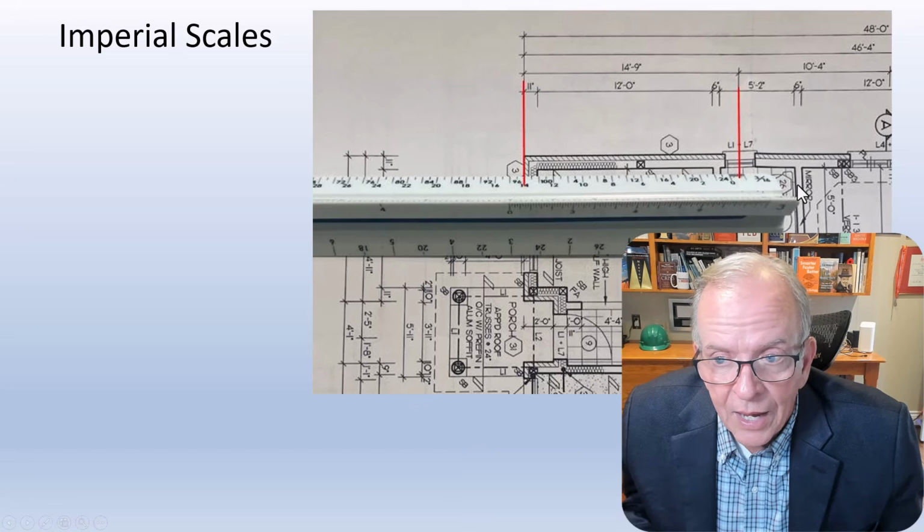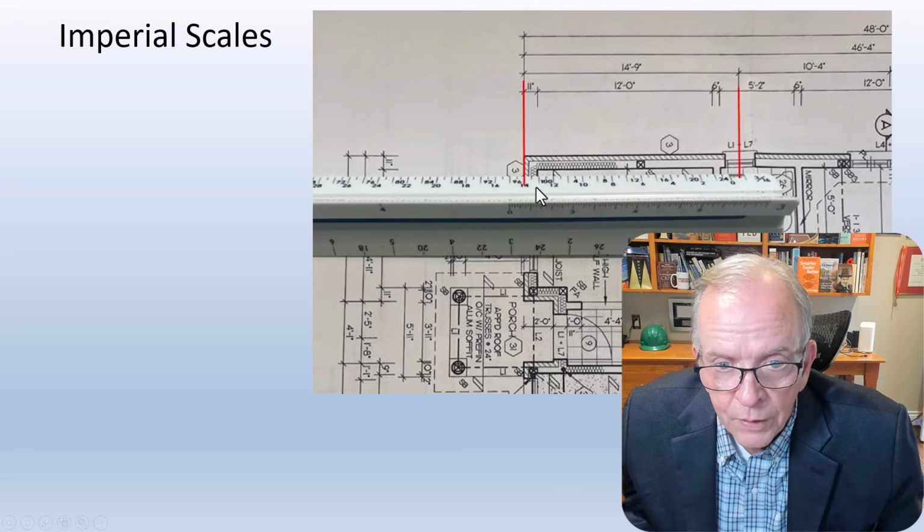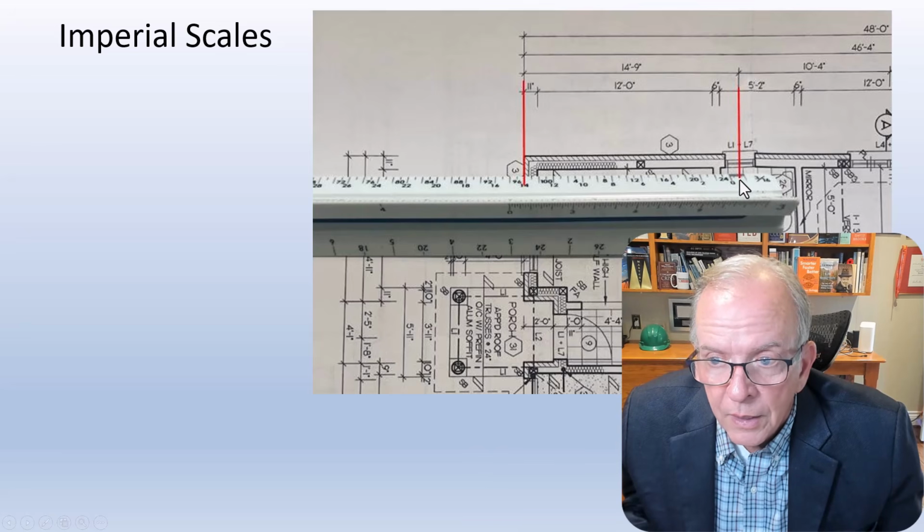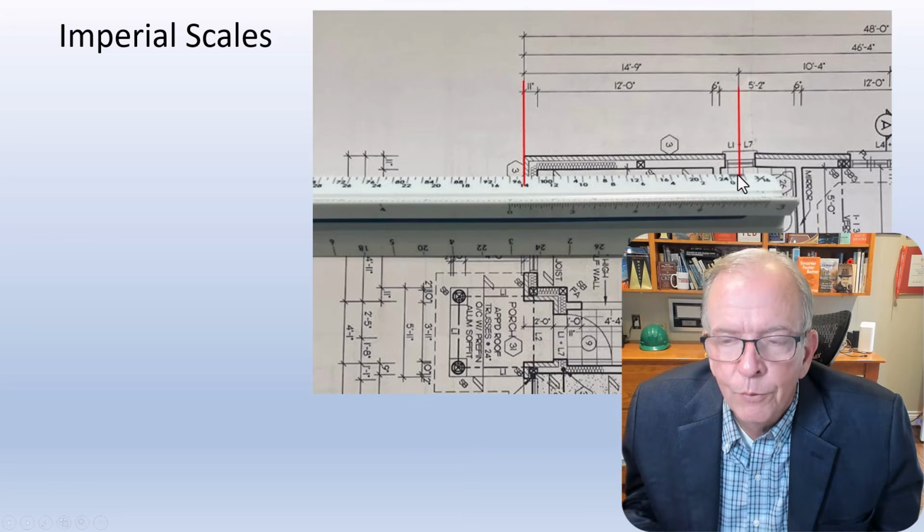And you could lay it down and you could say, okay, I'm using a 3/16 scale, right? So there's 2 foot, that's 1 foot then. There's 2 foot, there's 4 foot, that's 3 foot. Okay, 12, 14 foot. So coming from this line, 14 foot to this line here, I just overdid it in red. Okay, that's 6 inches, right? So it's coming in at about 14 foot, maybe a little blurred there, but right where it's crossing over here, that's at 14 foot 9 inches.